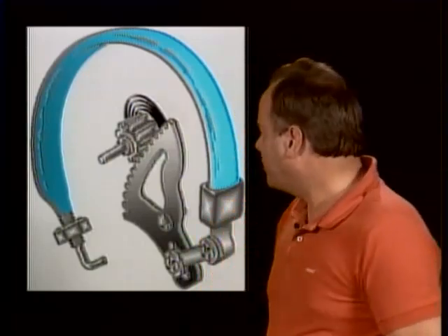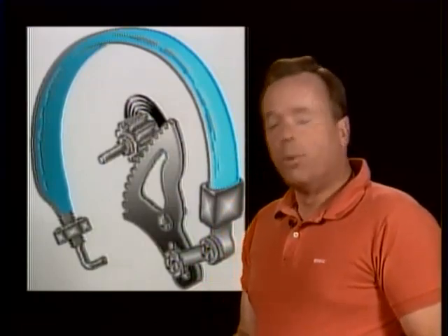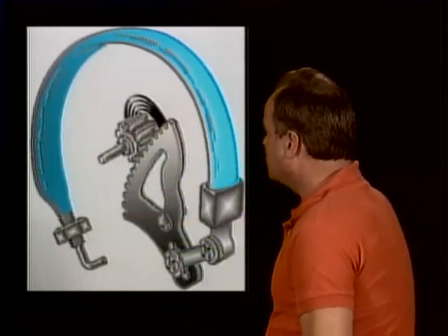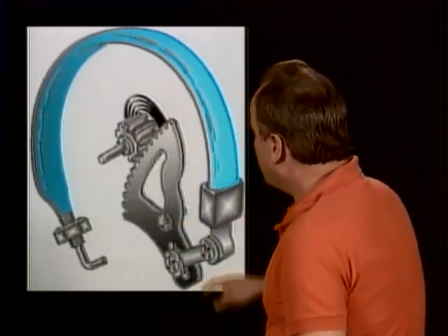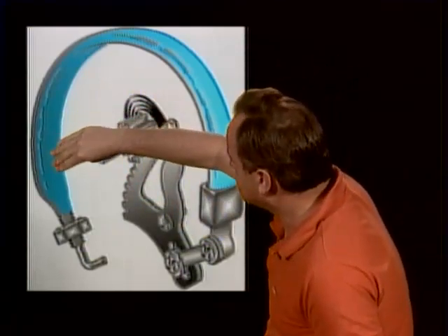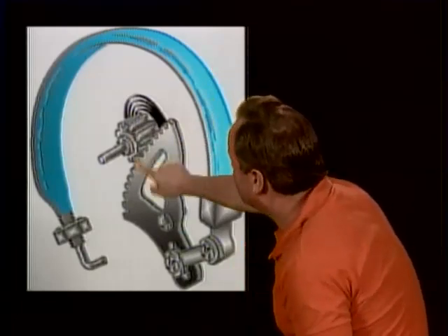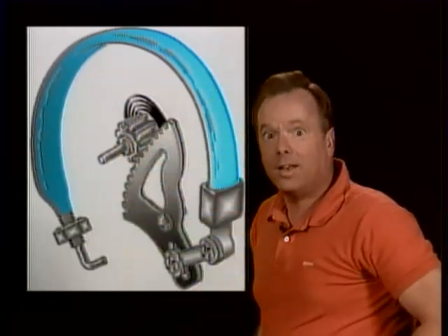All right, now, they're going to ask you about construction and design of various type gauges, and they're going to say instruments that provide readings of pressure of about 10 psi, such as pressure gauges and oil pressure, are usually of the Bourdon type. And here is a Bourdon type gauge. The way a Bourdon type gauge works, by the way, is you have a pressure inside this tube, which has kind of an elliptical shape. And when the pressure increases, the elliptical shape of the tube wants to become circular instead of elliptical, and that wants to straighten out the tube, and you measure the rate at which the tube straightens out on a dial, and it tells you the pressure.